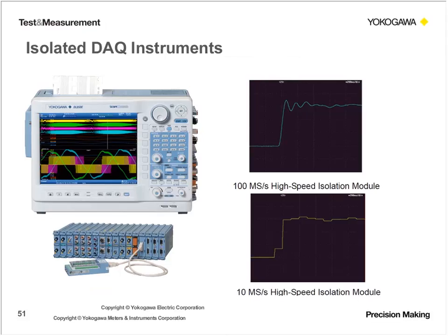So an example of this is when you're dealing with a pulse signal, if you don't sample enough, what you can end up with, in that lower screenshot, is this stair-stepping effect, which is that quantization noise. But if you're capable of oversampling or having a higher bit resolution, you can really eliminate that stair-stepping effect and improve that recreation of that original signal.